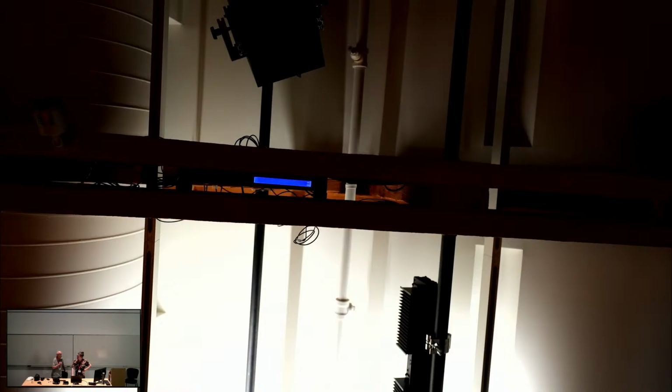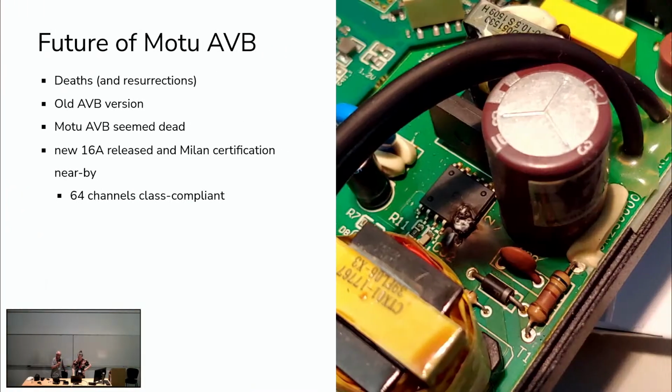The problem with the Mod2 interfaces is they're sometimes dying. It's been many years, and here's an example. You can see the switching power supply control integrated circuit that developed a hole explosively. So the holy smoke that's inside that makes it work escaped, and it's dead. We've been resurrecting some of them because I found an online supplier of power supplies, which is the first thing that apparently dies on these old things, which are now more than 10 years old.